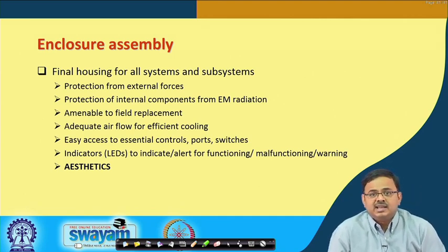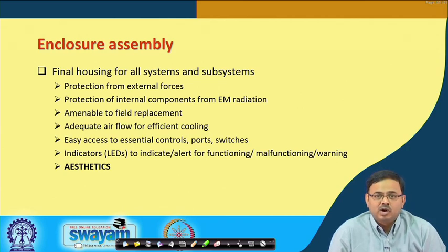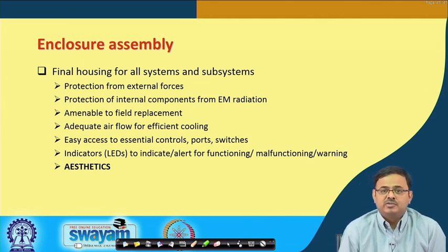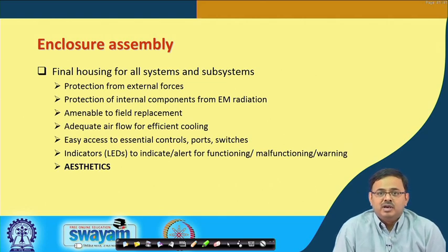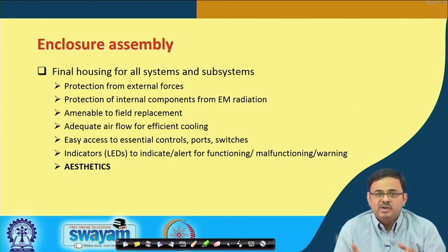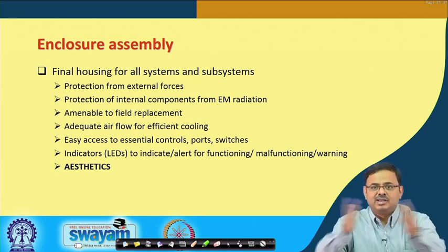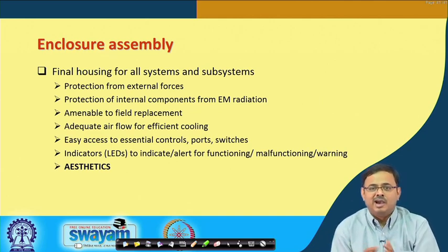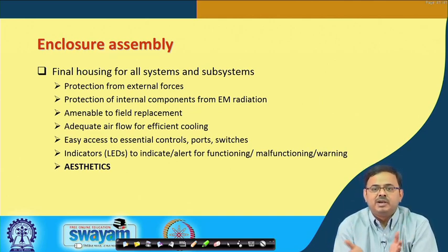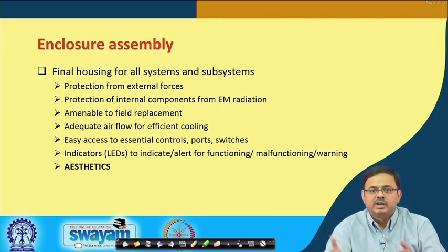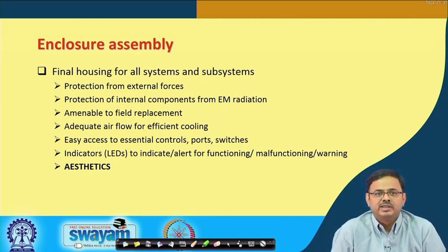So, chassis design is important, especially as we are going to talk about thermal design later, and it has a great impact on the airflow inside, both in terms of how much airflow in cubic feet per minute, or CFM, and the flow path. If you have a cooling fan, you have to direct the flow towards the hot components. How do I do that? So, the chassis design is not so trivial. It is not just like an enclosure where you take a sheet metal, fold it to your desired shape and just put it around the system. It has more to do with that.